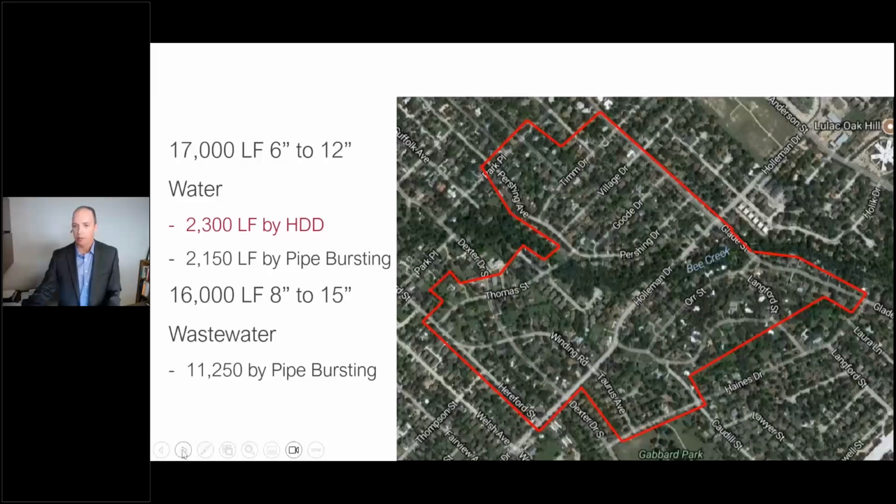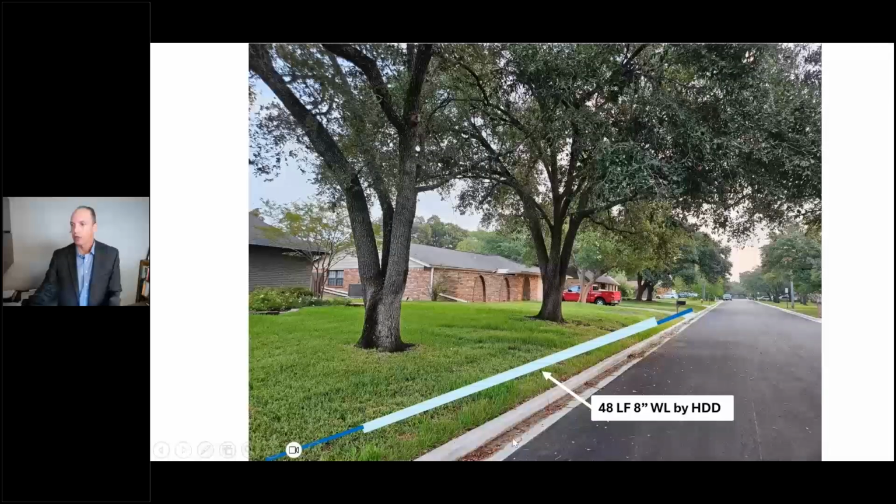As I mentioned, the majority of the areas where we utilized it were in short segments, typically probably 50 to 100 feet HDD drills, to minimize disruption to trees like are shown here on this exhibit. In this area, we were installing the water line just a couple of feet behind the back of curb. The majority of this is being installed by open cut through here.